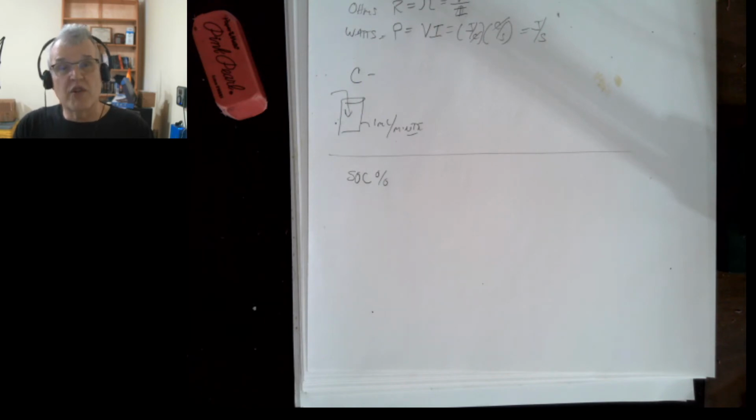Now, the lower the internal resistance, sort of the better to a certain point, and that's because if I'm using a battery for some work and it's discharging, then the discharge is going to go through that resistance. Of course, the resistance typically dissipates the energy in heat, and that means the battery is going to heat up. So you don't want a battery with a high internal resistance.